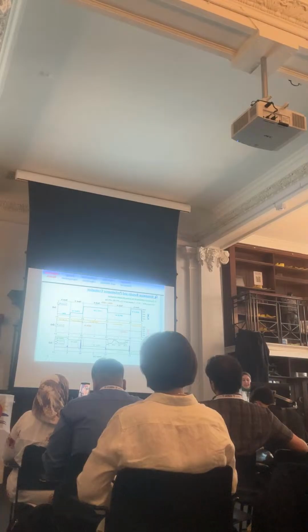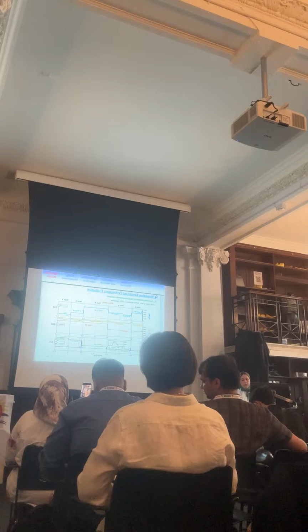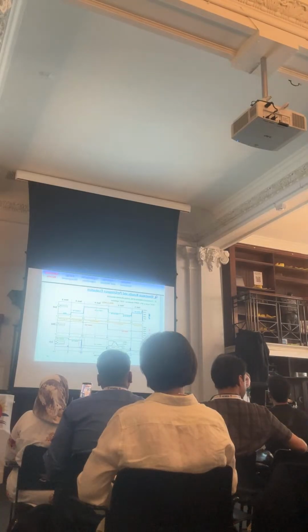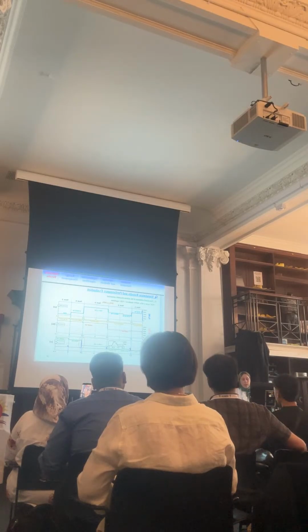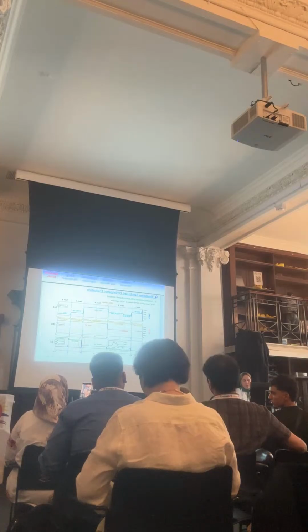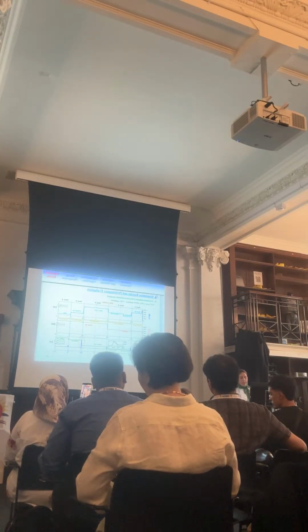This result demonstrates a stable DC bus voltage, intelligent power sharing, and fast adaptation to changing operating conditions. When the battery reaches 28% state of charge, the control strategy automatically switches from MPPT to DC bus voltage regulation, with the PV system supplying the load directly. As the battery state of charge decreases, the controller returns to the MPPT algorithm.